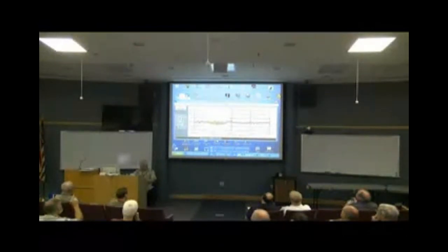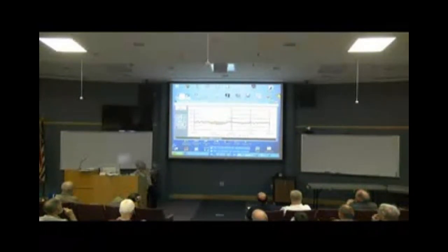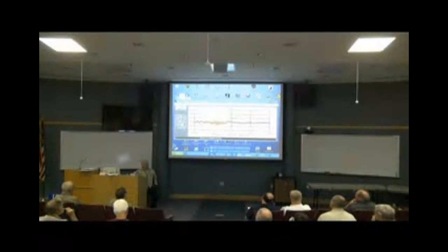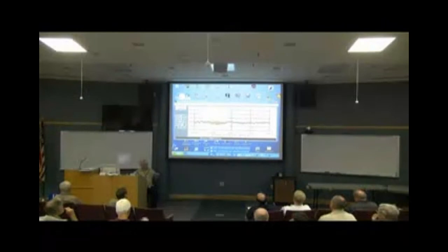Hey, Jim, what are the units on the y-axis? Well, I didn't look to see how he has it calibrated. I don't know. Now, normally when you're looking at a sound card, the values on this chart are just the values that come from the ADC in the sound card. Somehow that's been tagged as the SkyPipe values, and that's just uncalibrated. But we're going to show you in a minute how to change that into something more meaningful, into degrees Kelvin antenna temperature.